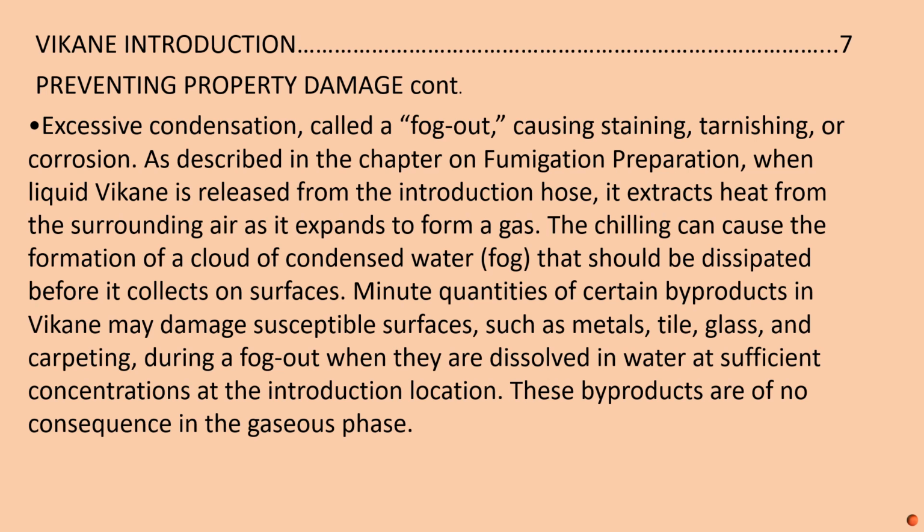As described in the chapter on fumigation preparation, when liquid Vikane is released from the introduction hole, it extracts heat from the surrounding air as it expands to form a gas. The chilling can cause the formation of a cloud of condensed water, fog, that should be dissipated before it collects on surfaces.